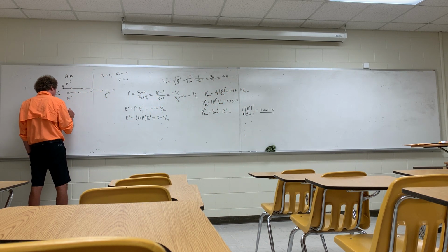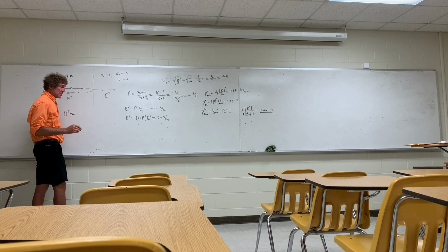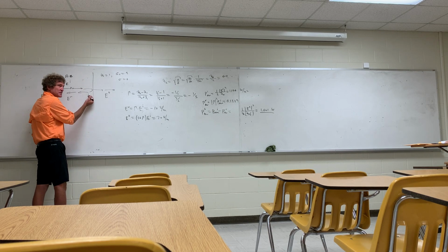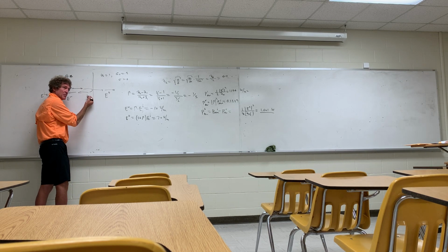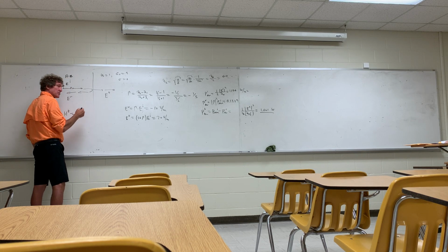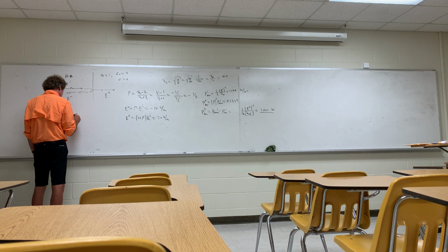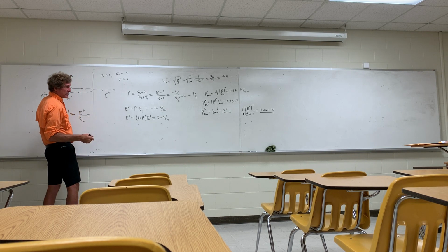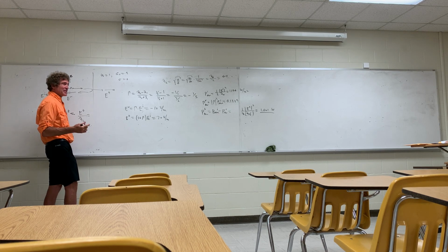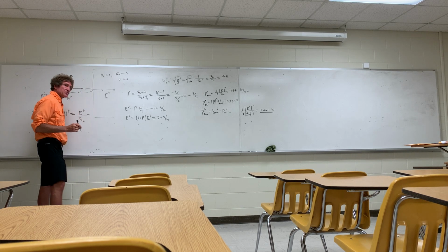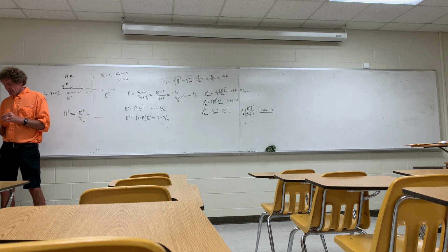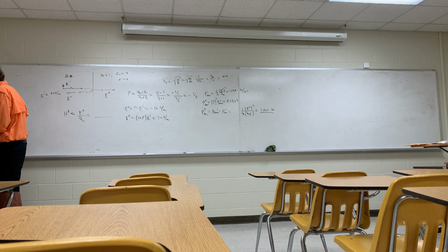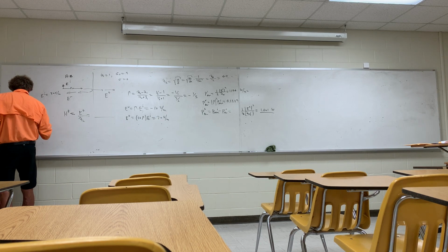Divided by 82. Right, 82, not 81. And you don't take the H field on this side multiplied by the transmission coefficient, you'll get a wrong answer. What you're going to do is take H, this is going to be equal to E transmitted over eta in region 2. Can you just give that to me, just because I want to make sure I state this explicitly today. So when people are watching this for the final, at least they'll have a note.